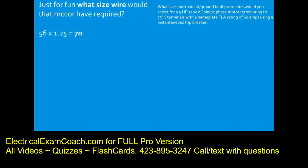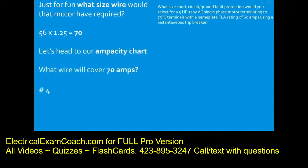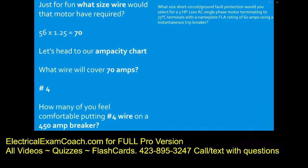So we size the conductors like this. We would take that 56 amp FLC, multiply it by 125%. That's going to give us 70 amps. Now we head to our primary ampacity table. We size the wire. It's going to be a number 4. So legally in this situation, you could put number 4 wire on a 450 amp breaker. Okay, now that would be the original breaker that you did back at the original panel. You would still have overload protection, but still, it's just outrageous to think that you could put number 4 wire on a 450 amp breaker.